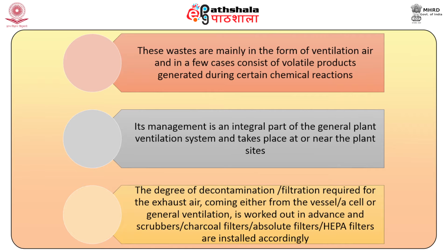The degree of decontamination filtration required for the exhaust air coming either from the vessel, a cell or general ventilation is worked out in advance, and scrubbers, charcoal filters, absolute filters, HEPA filters are installed accordingly.